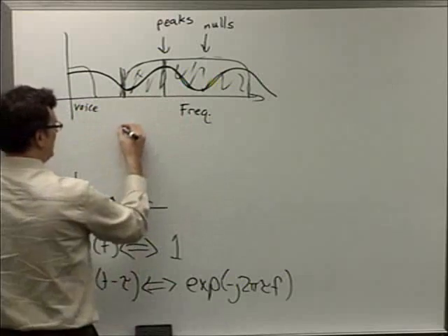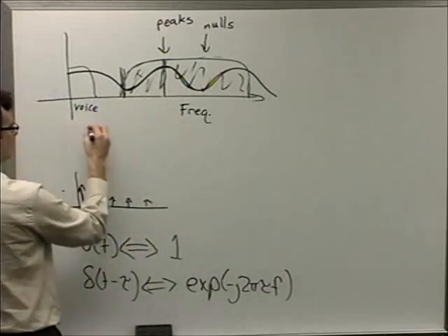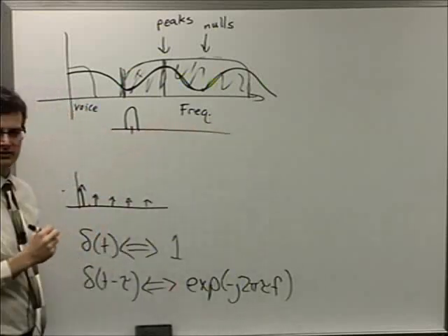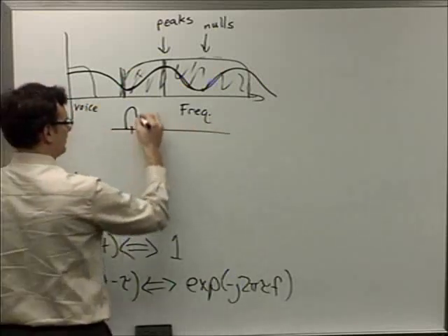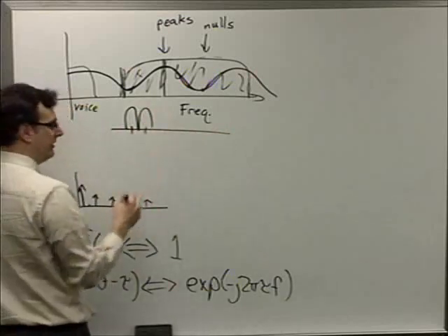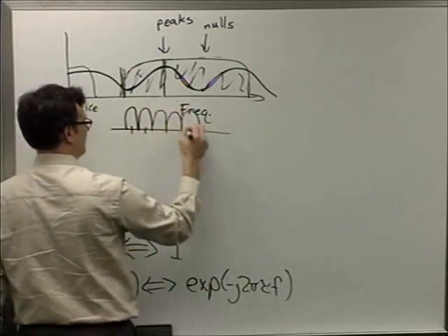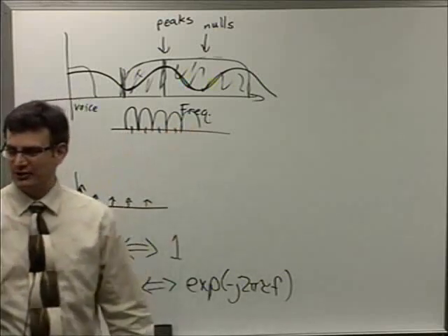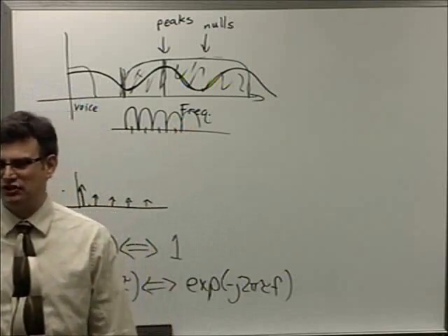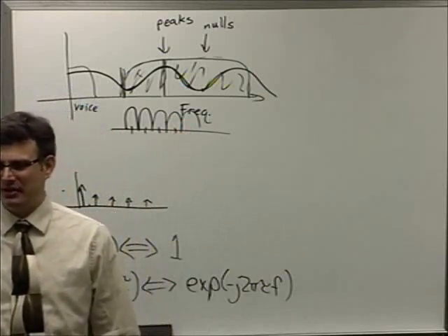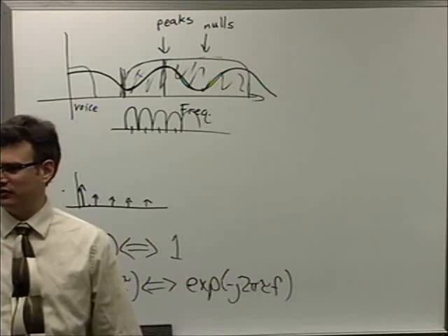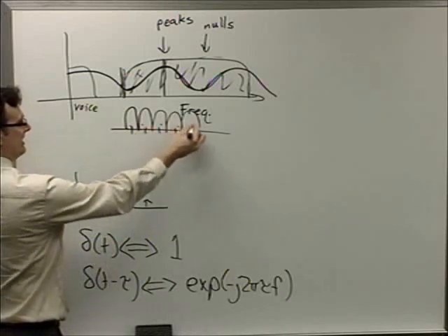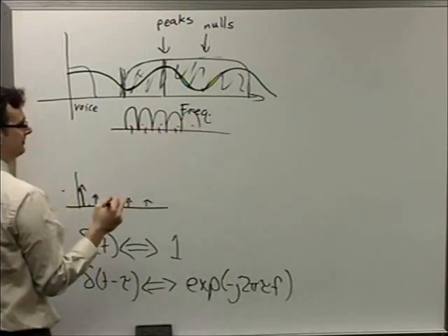There are actually several different schemes for implementing DSL, but this is one of the most common ones. You take a slow signal, which doesn't have a lot of spectrum, and you put it there in frequency. You take another slow signal and put it right there, right next to it. And then another one, and then another one, and then another one. So the individual slow signal, we know that slow signals don't experience much distortion on those transmission lines. You might ring them in the front, but you can use low-pass filtering to get rid of that. And so all of these will be easy to individually demodulate.